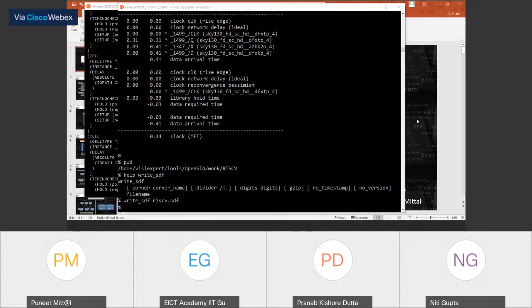If you are going for a design from scratch, you don't have any idea about the design, what the delay value is going to be, then what happens in synthesis? The first time when you do the synthesis, it is going to consider everything as zero. Then you will move to the next stage, maybe the floor plan and placement, and then you will see there are some delay values, but that's not the correct value, because with those values you're not able to close the design. So what happened? There are certain things which are like an approximate thing.